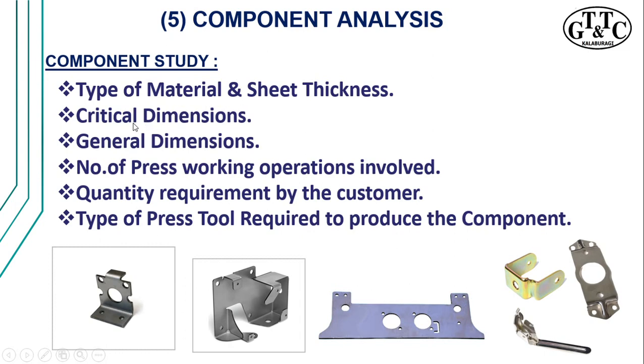Now the second point is the critical dimensions. Sometimes the component has some critical dimensions in it. They are very important because a component may go for an inline assembly with another component. So the dimensions are very important and critical. So it's very important to understand whether a press tool may be able to satisfy these particular critical dimensions.